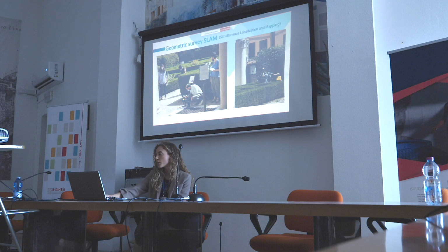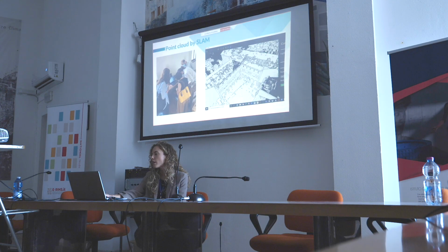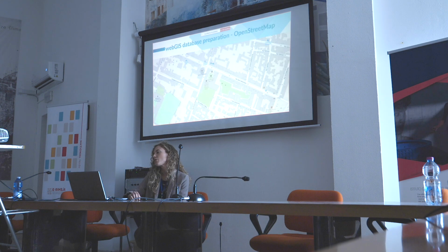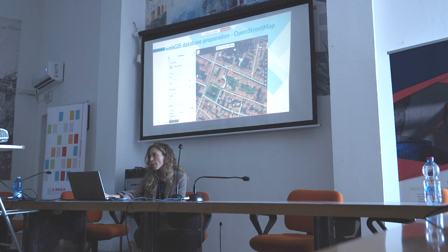The geometrical surveys was carried out integrating photogrammetry and SLAM laser scanner, and the in situ survey, including the entire building plus its open spaces and courtyards, lasted less than 1 day. Then a point cloud was developed in the post-processing phase and positioned inside a WebGIS application, improving the procedure that was already implemented and used in PROSIT.